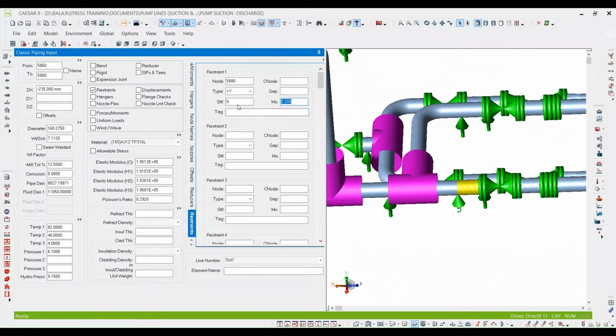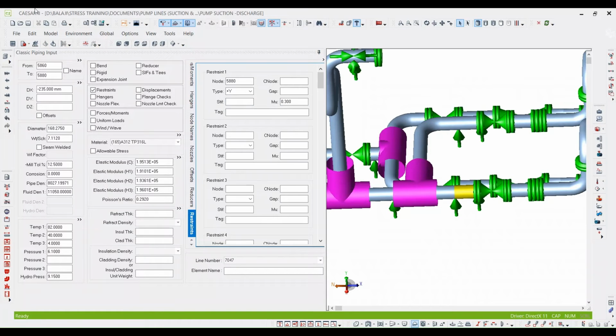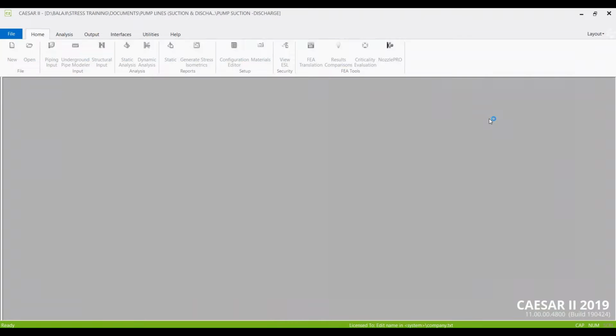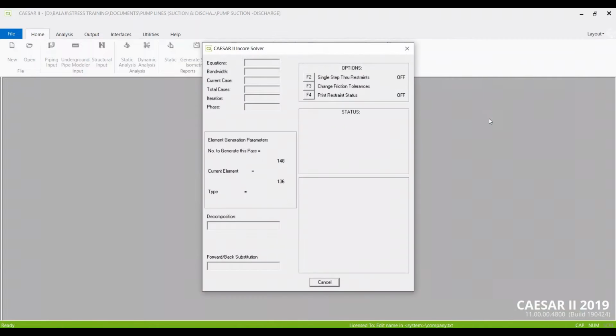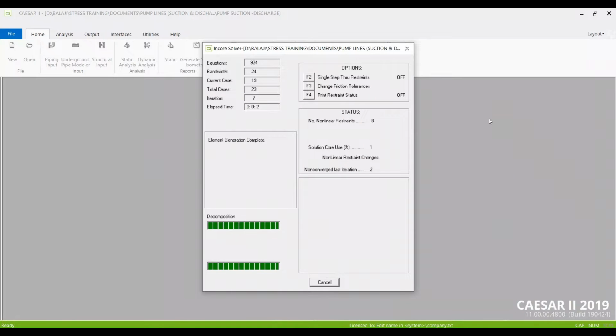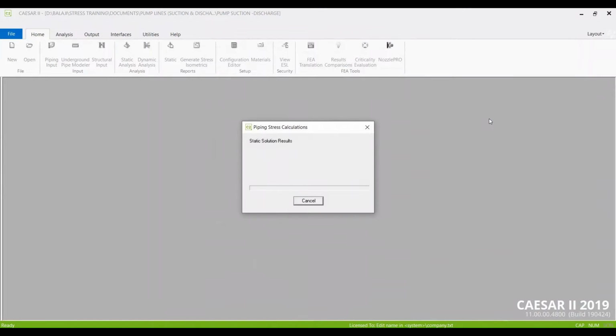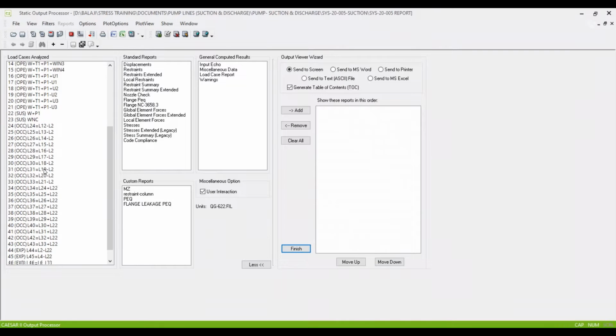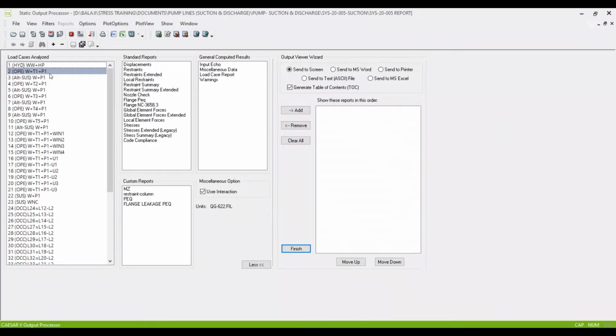So once the sustained deflection is within the allowable, we need to check the horizontal deflection. For such small lines, there will not be a big problem in the horizontal directions, because for the pipe rack lines, the lines running on the pipe rack or the main steam lines only will have the issue of thermal expansion. So now we'll see.